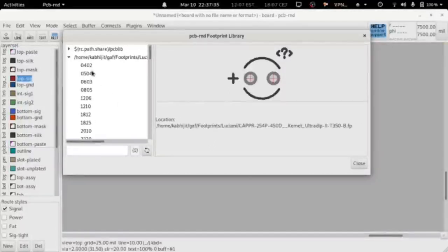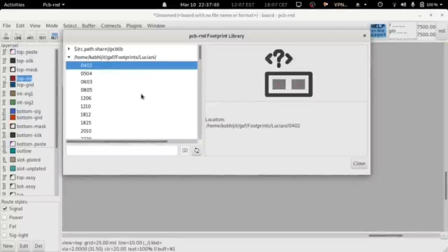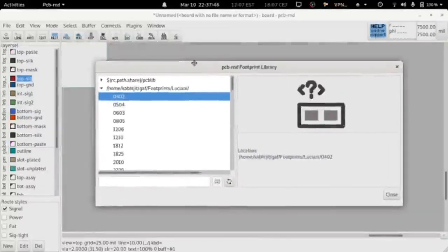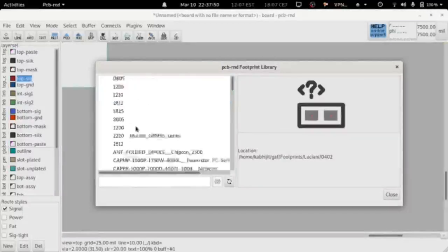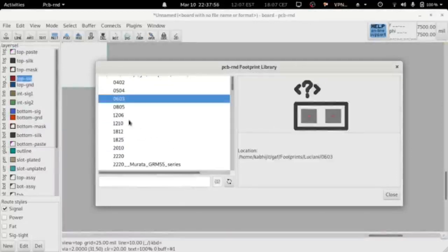So now when I want to use a particular footprint in my design, for instance 0402 or whichever footprint I want, all I need to know is the name. That is the footprint name. If I copy that name into my schematic file, then that's how my schematic editor knows what footprint is to be used when I do the layout.